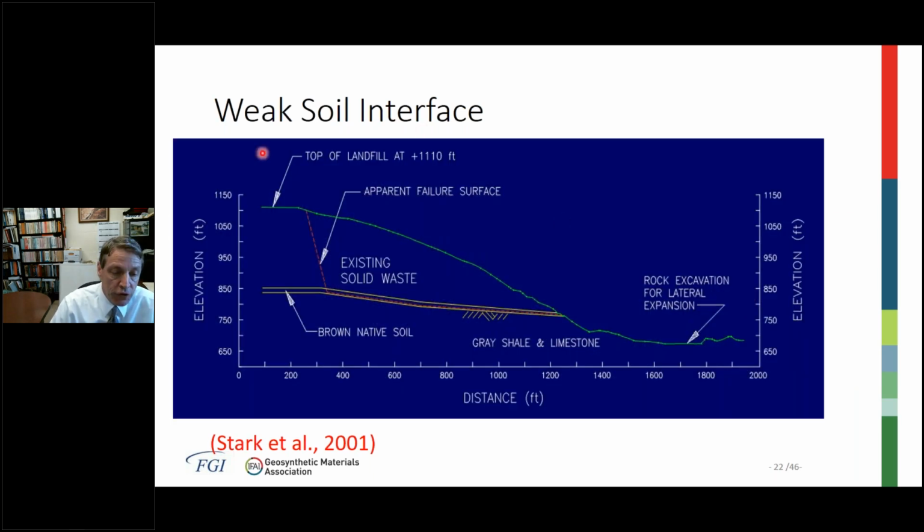And here's the failure surface going steeply through the municipal solid waste along the brown colluvial material and out through the toe.